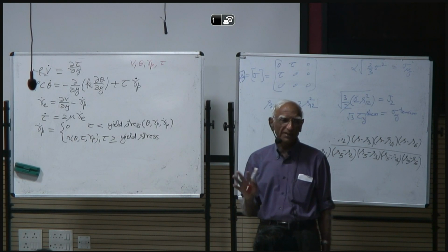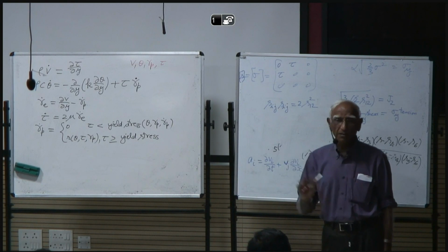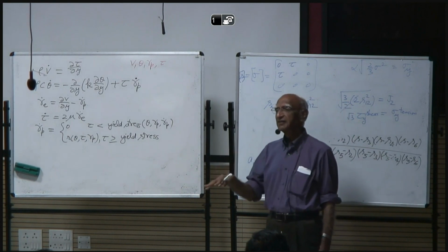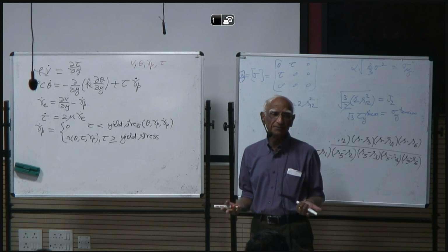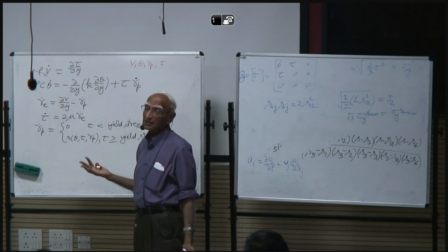You know where I'm getting at? If you have a small defect, which becomes locally heated somehow, then plastic deformation near that point will become very large. You cannot avoid it, because the material is thermally softening.